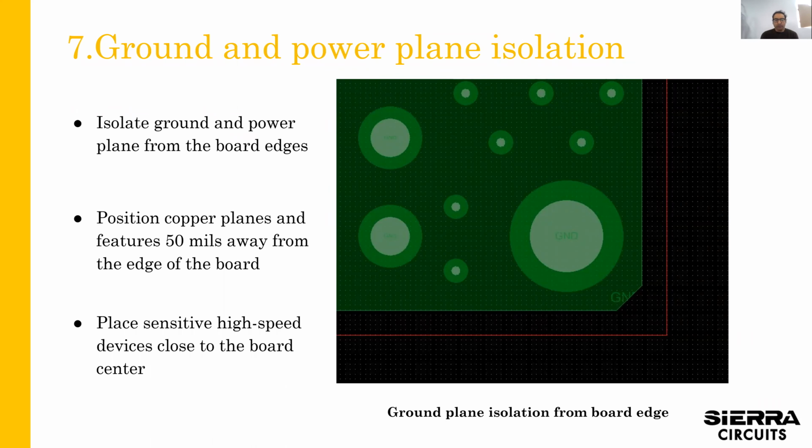I think the point here is that when you're designing your ground copper pours, be very careful about that. You don't want any copper right up to the edge of the board. So when you route your board, there's an issue going through copper. You don't really want that unless you have castellated edges, in which case you have to follow the design guidelines for castellated edges.